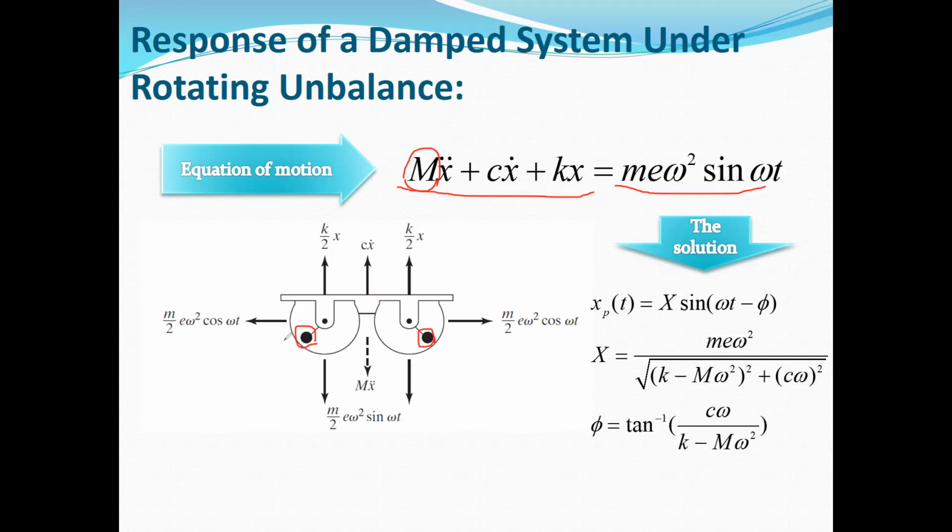So the effect of these unbalanced masses is similar to external forces or base excitations, and they will affect your equation of motion as a non-homogeneous term, and will not appear in the mass of the system. In your equation of motion, you can see that the coefficient of the acceleration, which is the equivalent mass, is exactly the mass of the structure, and the coefficient of x dot is the damping coefficient, and the coefficient of x is the stiffness of the structure.